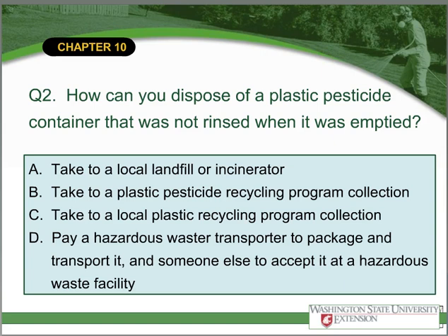D. Pay a hazardous waste transporter to package and transport it, and someone else to accept it at a hazardous waste facility. Answer D. If a rinsable container is not triple or pressure rinsed, it is considered a full container and usually requires disposal at a hazardous waste facility.